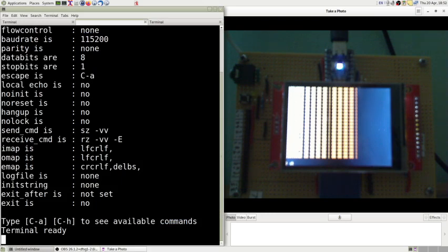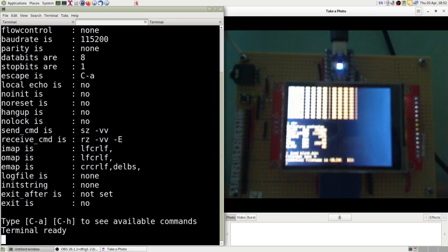So dir, and we can see a program called Blink, which is 82 bytes long. So I'm going to load that into a fixed position in Flash. So I'm going to type load blink.bin. That's done that. And I'm going to run it and see what happens.